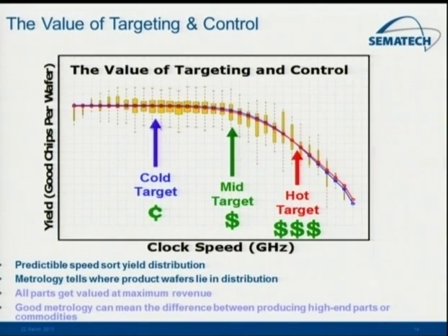And this is referring to the cost part of it, which is you have two things you're always looking at, or not always. In the case of microprocessors, what you always look at is what's the yield? What's the percentage of these that work? And then also, how fast are they? Because in some cases, if it's a faster part, you can actually charge more for it. But sometimes if you try to push the process to a faster product, your yield can sometimes roll off. And this was actual device data, it's not indicated what node it is here.